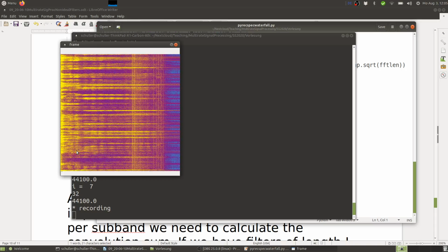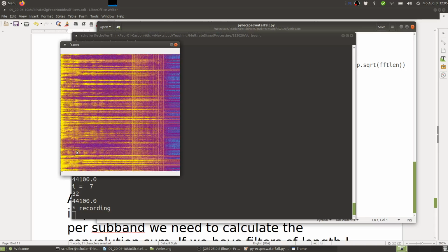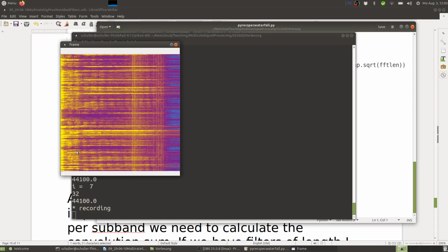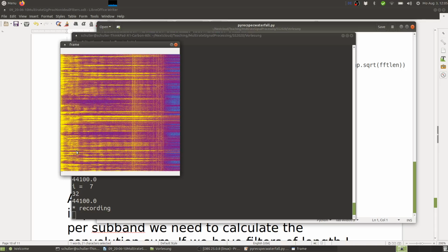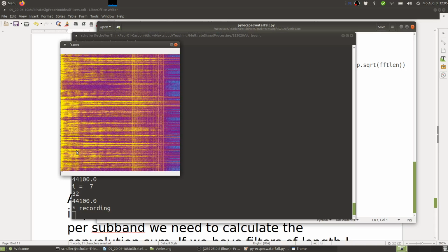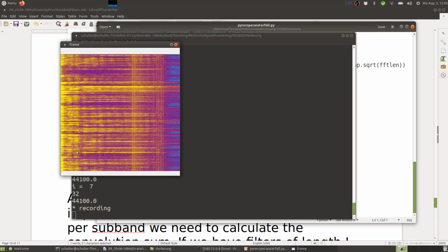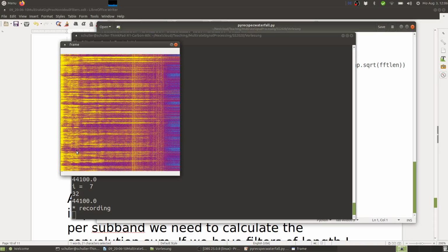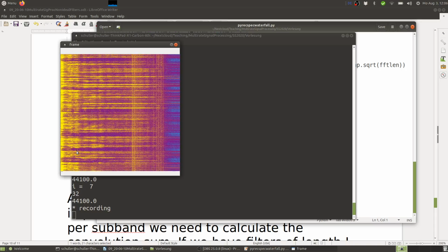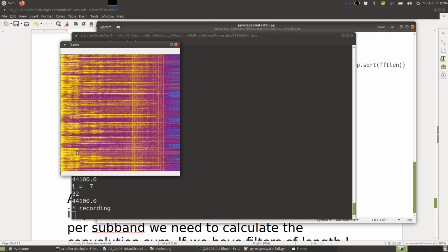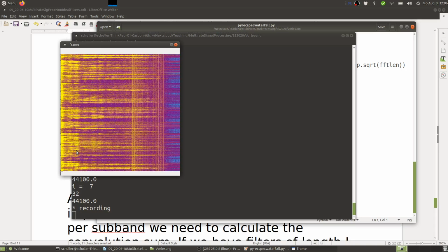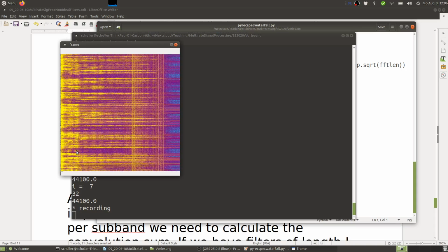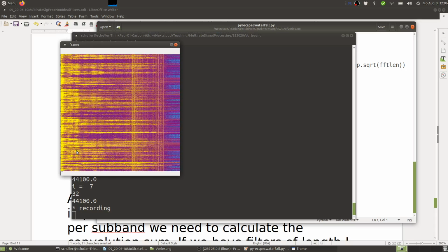Right. So this is an easy example of a time frequency decomposition, and if the FFT would be as big as my block size, then we could actually easily invert this time frequency decomposition by applying the inverse DFT. That's the advantage of having the DFT. We also have an inverse. And we already know that the DFT is basically a filter bank with pretty bad filters, so we have a lot of aliasing. And this shows it's actually possible to get perfect reconstruction despite the strong alias components.